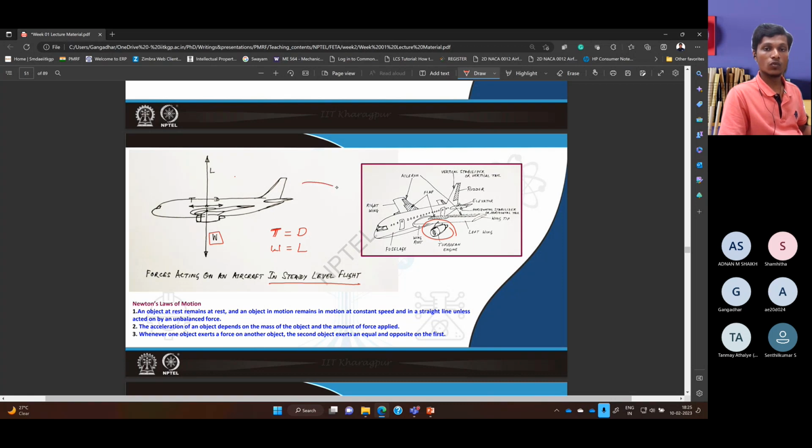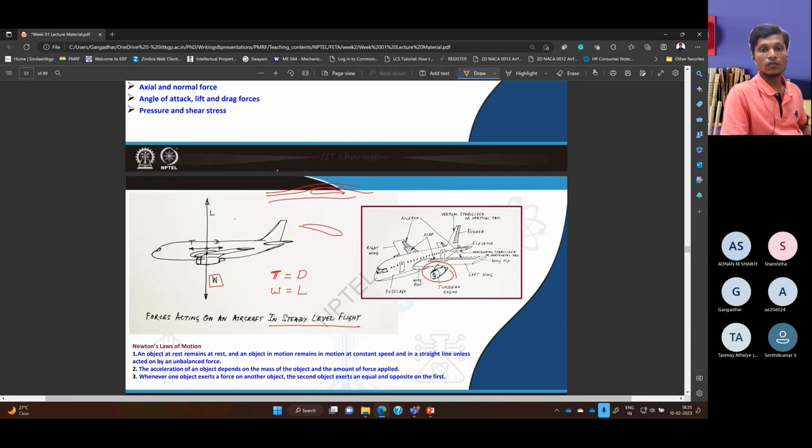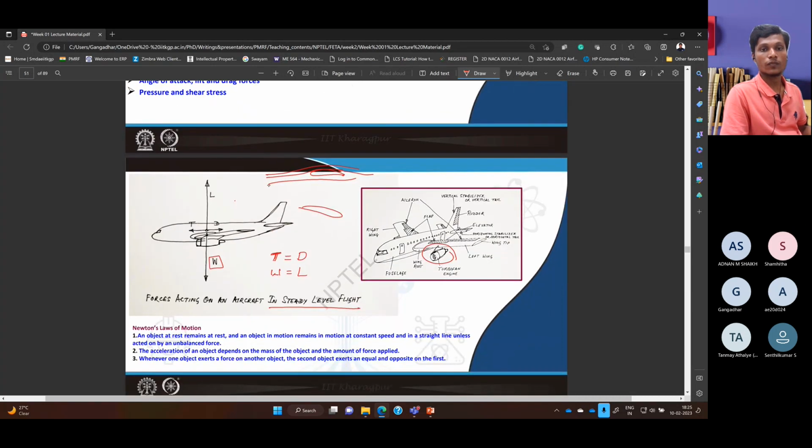As flow passes over the airfoil, you have already seen how lift is generated by some basic principles. The airfoil is turning your flow from inlet to exit. At the inlet you have the flow in a straight horizontal way as a free stream, but at the exit it will turn like this.